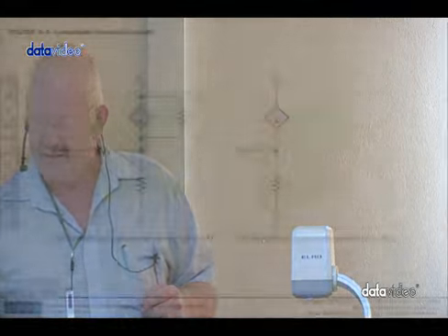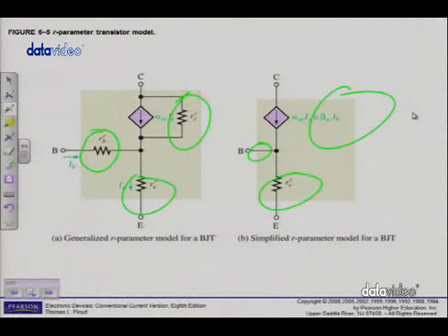We've seen if the diode is reverse biased, the electrons are moved away from the center. There's a very big resistance, so it acts as an open. Basically the same thing here, very high resistance, so we can regard it as an open. So the only one that's actually left is r'e. And there's the simplified circuit there.